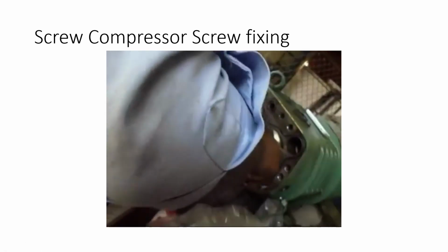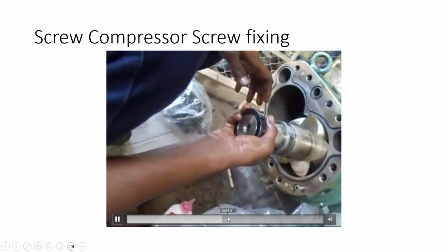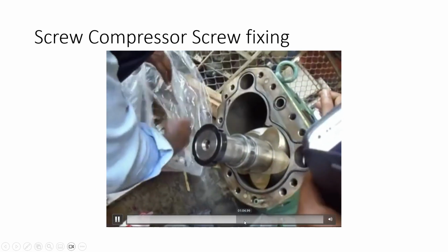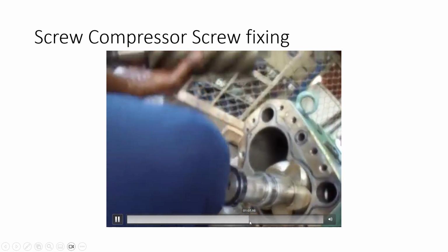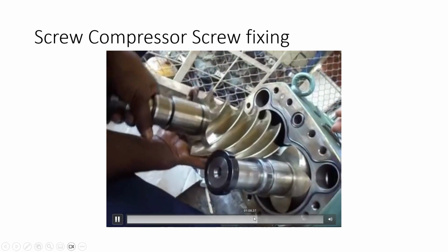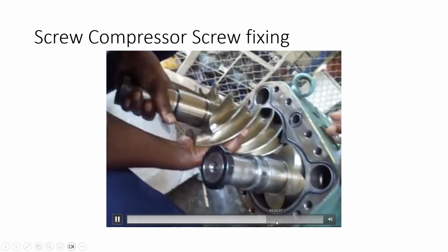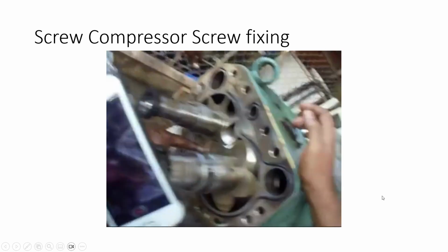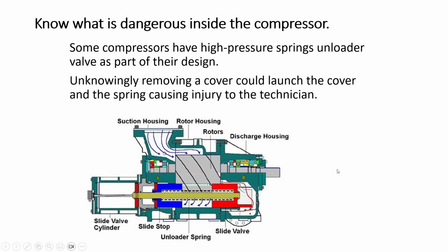After that, you will take out the second rotor, and you have to push it inside on the next opening, and you will have to slightly rotate it so that it is able to go inside fully. When it goes inside fully, you see the two are matched and the rotor insertion is complete.